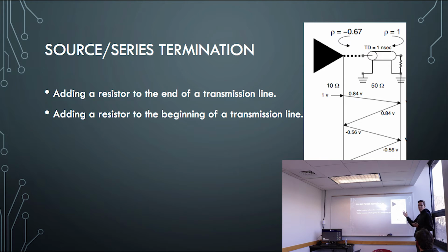So there's obviously going to be a pretty large reflection back, and as it gets to higher speeds, it's going to be more severe. So what you do is you put a resistor here. Say this is a 50 ohm transmission line, then you're going to put a 50 ohm resistor right here. So it keeps the characteristic impedance the same all the way across the line, and you're just reading at this point. So that's another way. Same thing right here. You can do the same thing. It just depends on what your application needs. Usually the easiest one is to do the end termination.